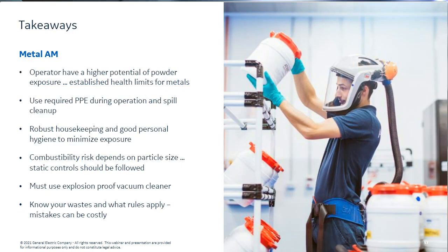Yeah, here from the occupational health and safety part, also some key takeaways. Operators that work day by day with these materials have a potential exposure scenario, which needs to be considered. Think about the right PPE that you use for your operation and what type of activities you have there. Housekeeping is key.